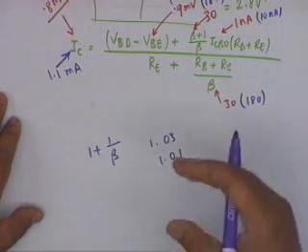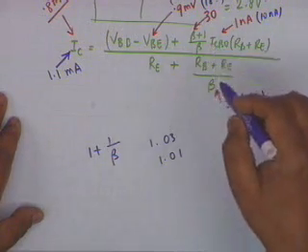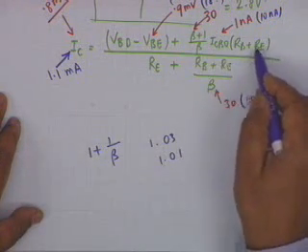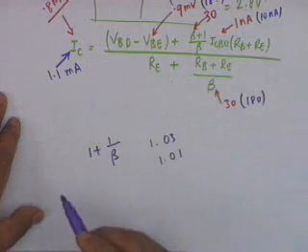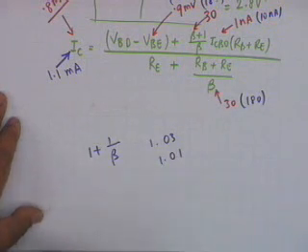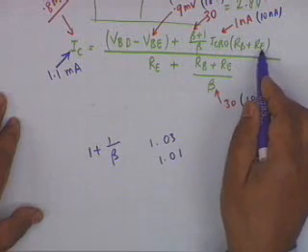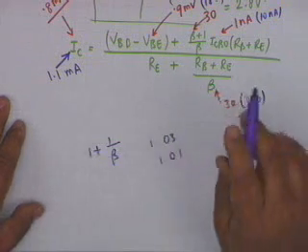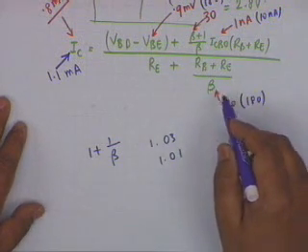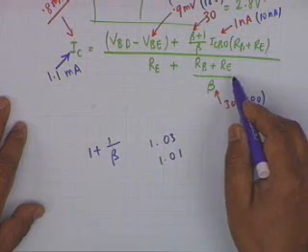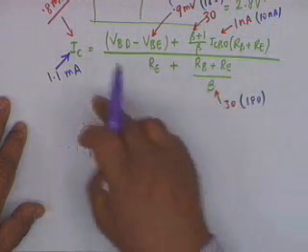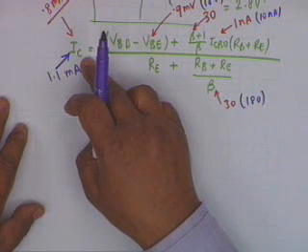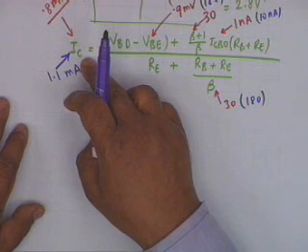The dependence on beta: there are two reasons why it doesn't make much of a difference what beta is. That is because ICBO is also typically a very small quantity, and therefore the total quantity here compares negligibly with VBB minus VBE, and therefore beta dependence is mostly through the denominator. And to make this insensitive to beta, what does that mean? It means insensitive to transistor replacement.